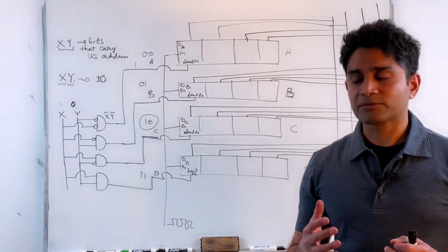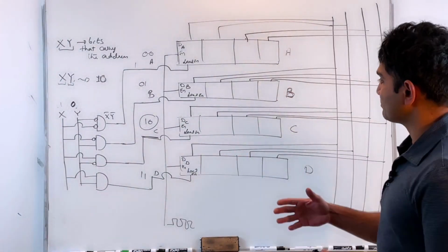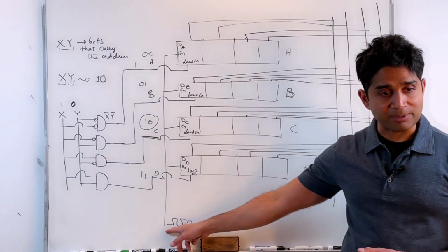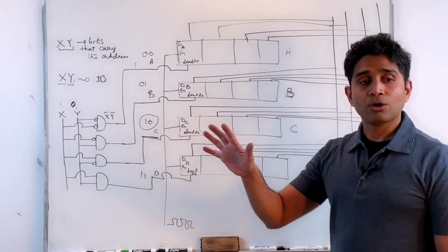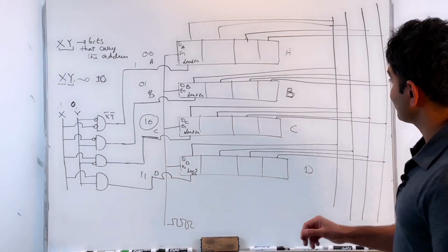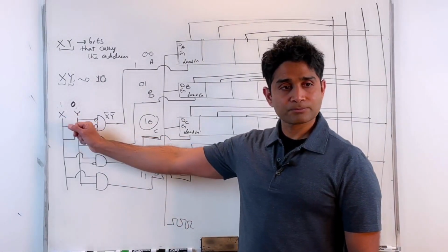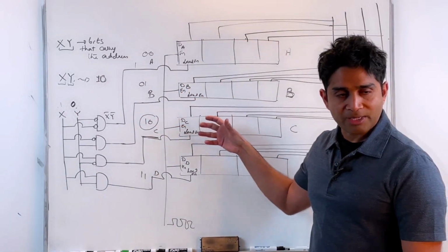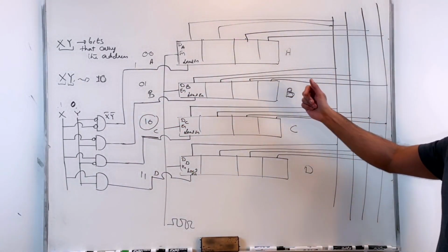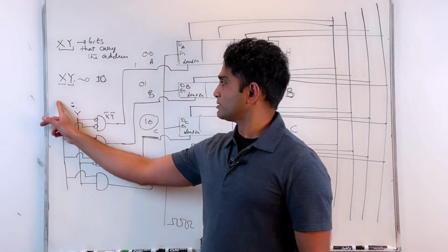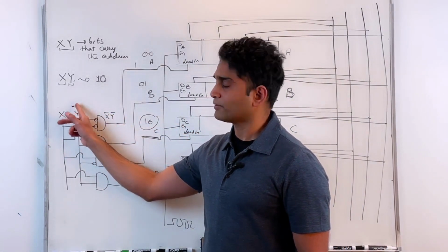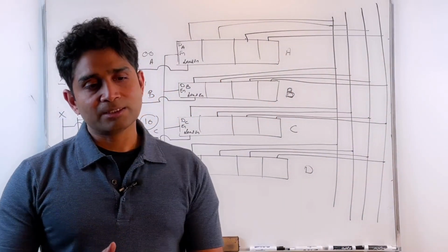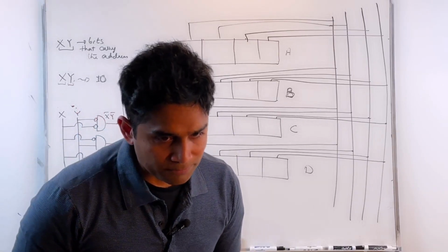And of course, I have to synchronize all of the actions with respect to the master clock. That means when I place the data on my data bus, I need to synchronize with the master clock. So basically, I need to place the data on an inactive level or edge, apply the right address, and on the next active edge, the data gets transported to my register, and then I would take that out and place a different value on my X and Y. So every activity is synchronized with the master clock that way.